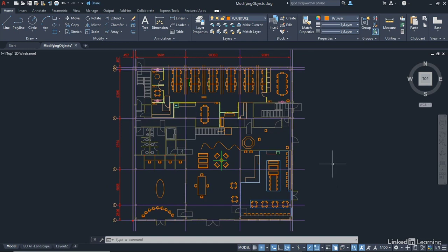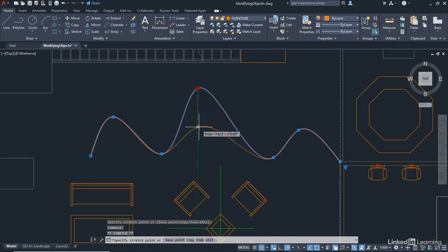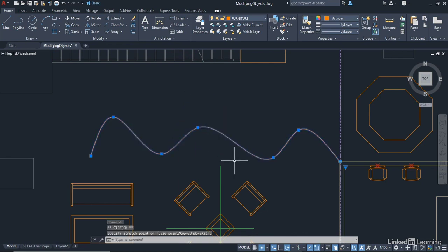Now, what we're going to do is have a look at editing polylines and splines. So we've just created a spline. Let's zoom in on it again and select it. Now, I selected a spline there with fit points. So each of those grips is where I clicked to place that particular spline. If I click on a grip and drag upwards, can you see I'm resizing the spline by moving up and down? It's always a good idea to utilize your polar tracking to do this, as you can see, and click like so. So my spline has moved.